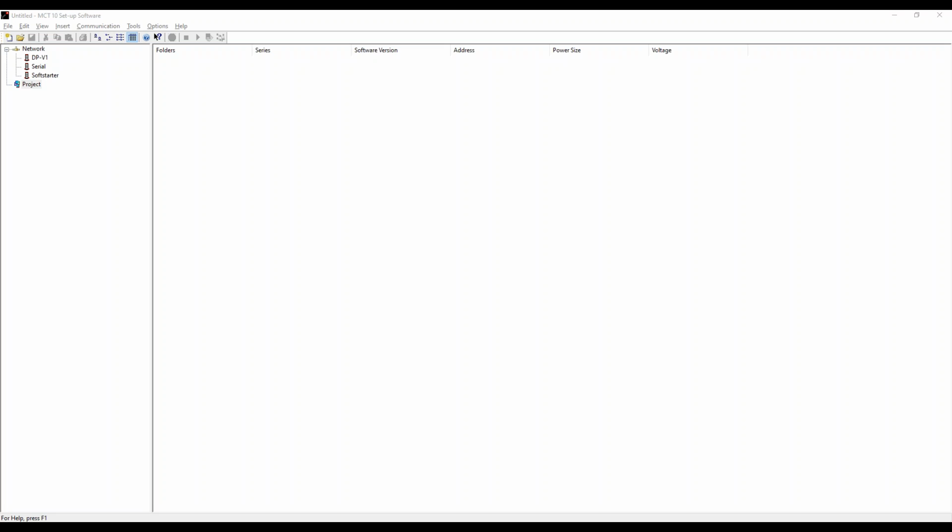Because I didn't turn. If you left start on that bit and you just cycled the coasting bit, when you take it off coasting, like you do on a terminal block, the drive will just take off again. Correct. So in the one example where I always had coasting on, it was bit 3. I had 2, 3, 4, 5, and I was toggling bit 6. So if I leave all the bits on and I just turn 6 off, it's going to ramp.